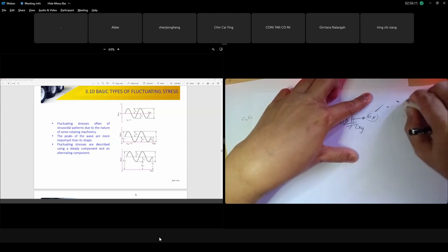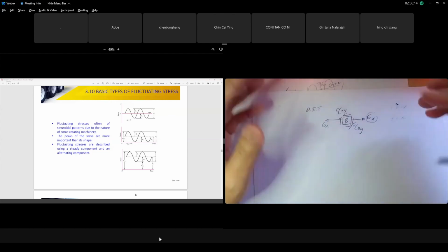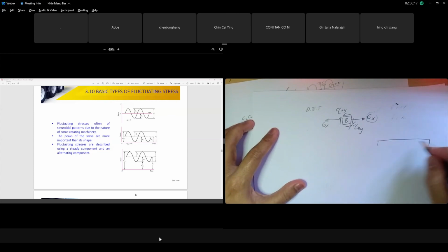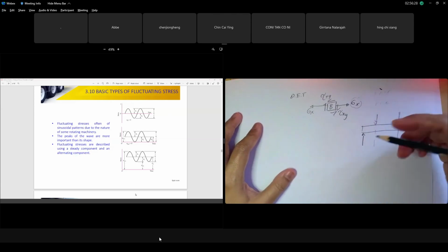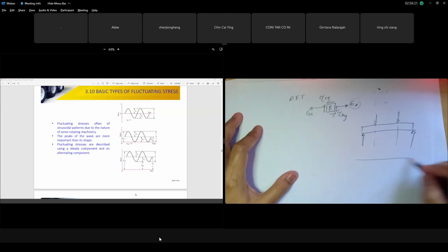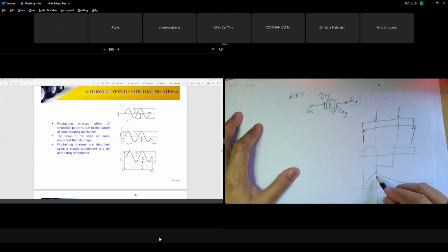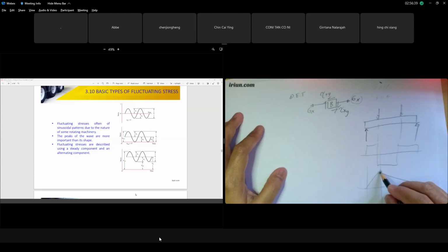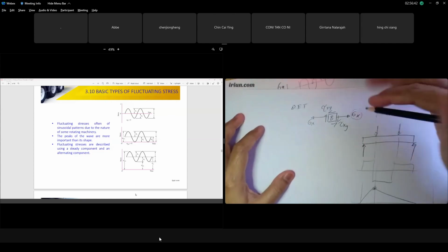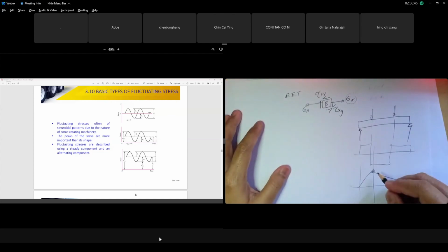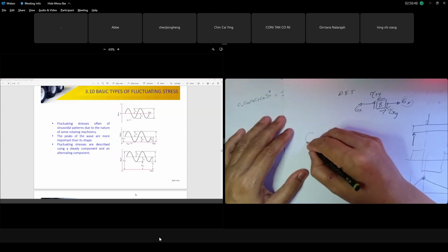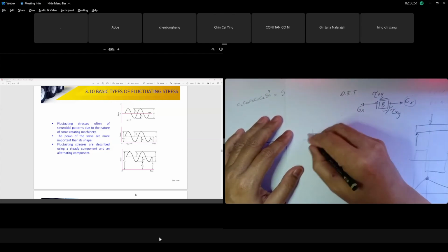Normally for a shaft, the equation does not give you a force range, because the shaft is rotating. Say you have a support here and a point where you mount your pulley, and this one is a gear. You already calculate your shear diagram, in the XY plane and XZ plane, and your moment at B, where both planes are critical. For shaft analysis, there is no maximum or minimum force. Your force is just one value, then you calculate your moment. But remember, the shaft is rotating. You look from the side view, the shaft is rotating.